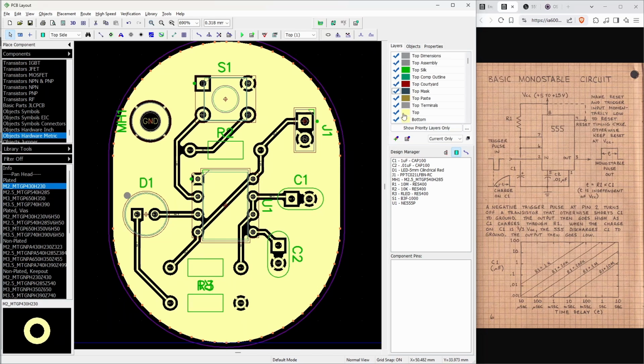So how do I get all the layers back really quick? Well, I'll just check them off. Okay, so this looks fine. Now, there are a couple things I don't like. The Silkscreen doesn't look great. J1, S1 aren't necessarily useful, and R2, it would be nice if it showed me a value there.